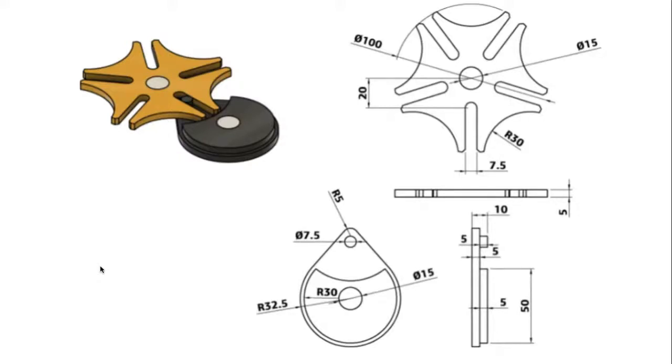And these construction models are very useful because when we are working with some extraordinary projects or very large assemblies, these construction entities can't be differentiated if we do not make them hidden lines or something, and it will cause confusion. So this feature of converting construction lines into dotted entities is very useful in Fusion 360.